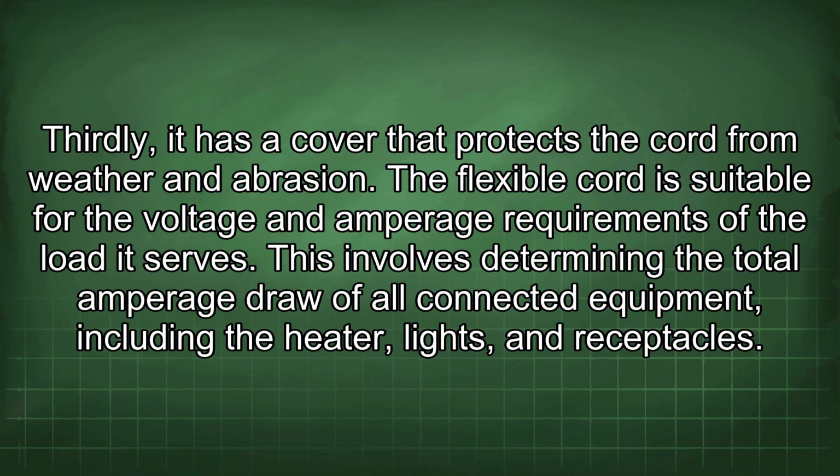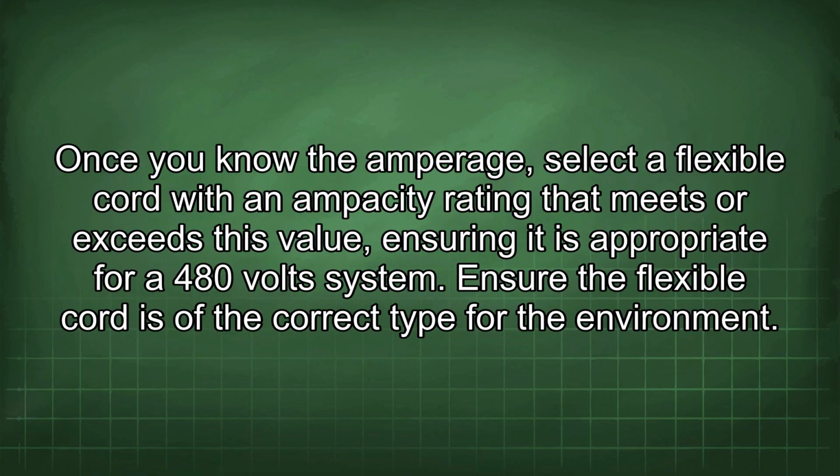The flexible cord is suitable for the voltage and amperage requirements of the load it serves. This involves determining the total amperage draw of all connected equipment, including the heater, lights, and receptacles. Once you know the amperage, select a flexible cord with an ampacity rating that meets or exceeds this value, ensuring it is appropriate for a 480-volt system.